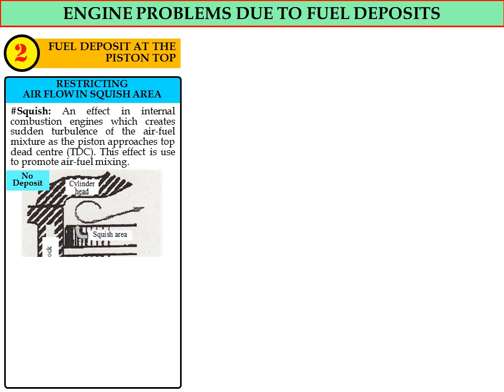So the figure shows what I call the smooth air or fuel flow in the squish area without deposit. At this condition, without deposit, we can promote air-fuel mixture due to the smooth air or fuel flow at the squish area.